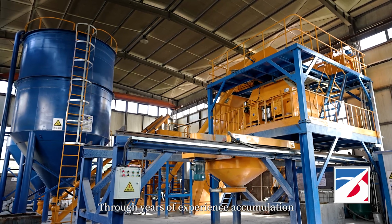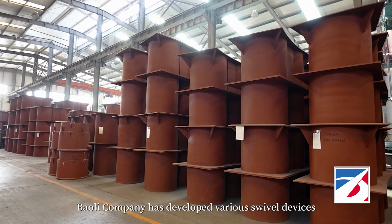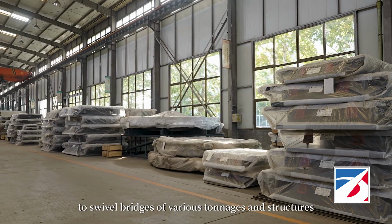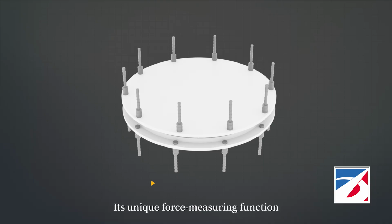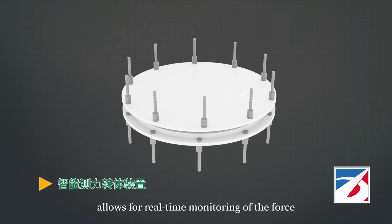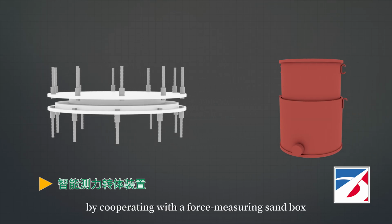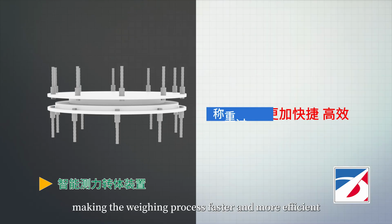Through years of experience accumulation and continuous innovation, Baoli Company has developed various swivel devices that can be applied to swivel bridges of various tonnages and structures. Intelligent Force Measuring Swivel Device. Its unique force measuring function allows for real-time monitoring of the force exerted on the support body during the swivel process. Additionally, by cooperating with a force measuring sandbox, it can achieve weighing work, making the weighing process faster and more efficient.